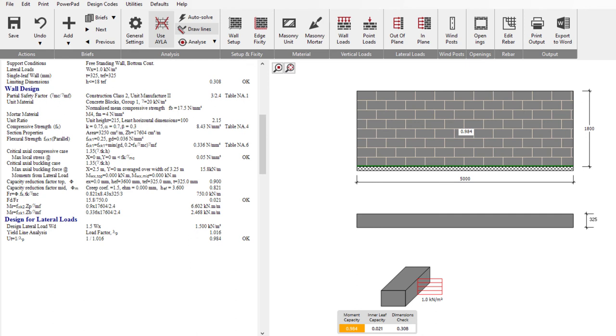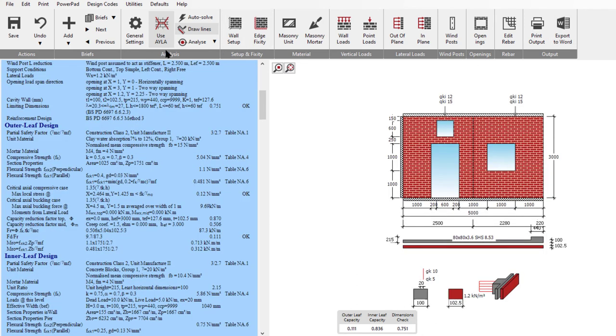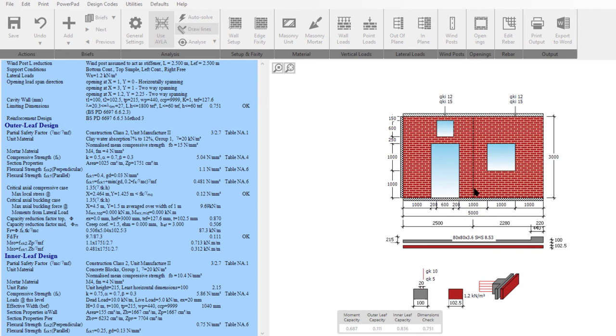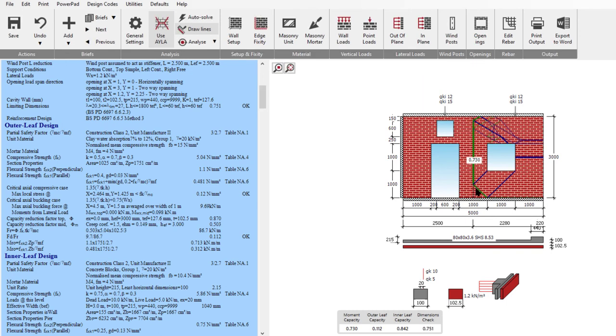When the yield line occurs, if you remember, and I go analyze, when the yield line occurs vertically down the edge of the post, then the post is not yielding but resisting the wall. But again, its contribution has already been taken care of in the analysis, so you don't need a second set of design on it.